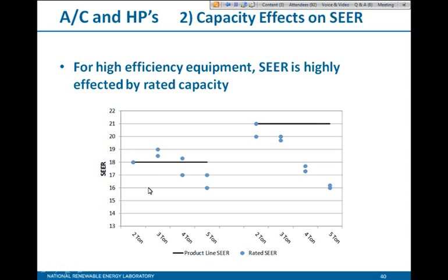And you can clearly see how for the higher capacity units, the SEER goes down by a pretty large factor. This is basically due to a cost and size limitation on the outdoor unit: in order to get a SEER 21 5-ton air conditioner, the outdoor unit would need to be huge. And so there's a limitation there in terms of what people will buy.